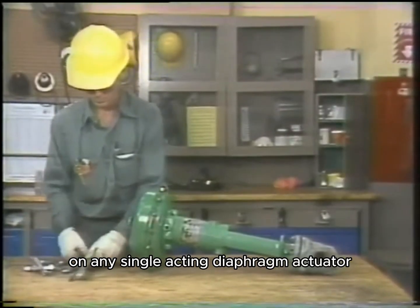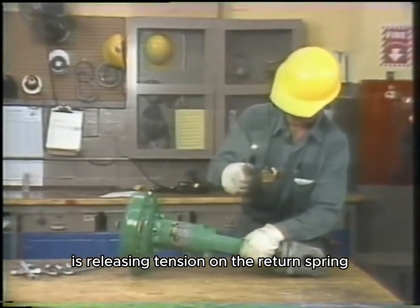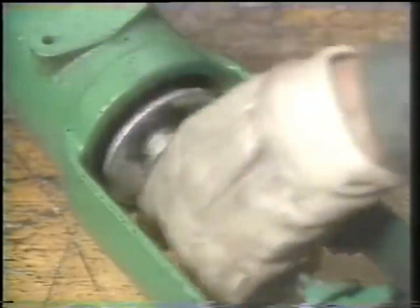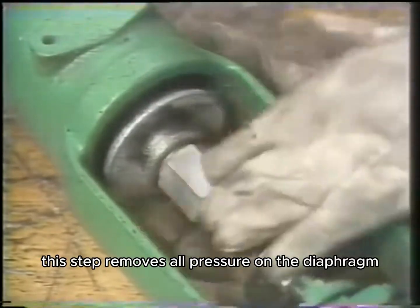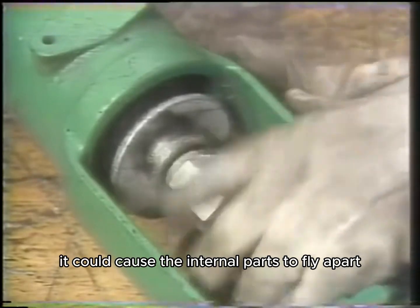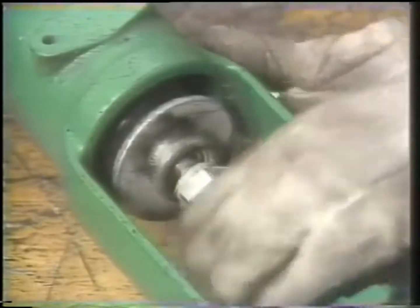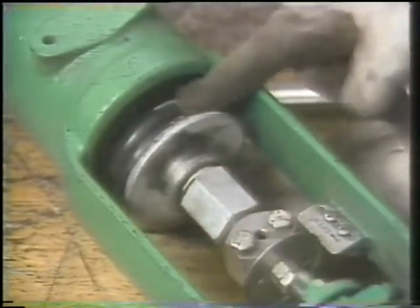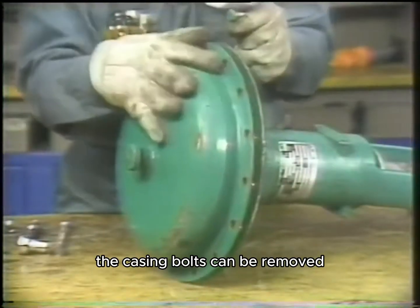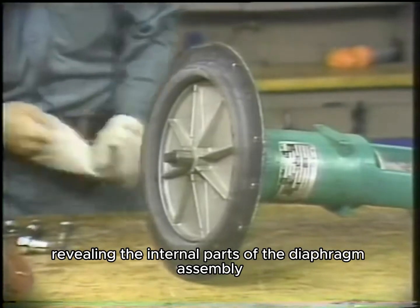On any single-acting diaphragm actuator, the first step in the disassembly procedure is releasing tension on the return spring. On this actuator, spring tension is released by loosening this nut on the actuator stem. This step removes all pressure on the diaphragm. If spring tension is not removed, it could cause the internal parts to fly apart as disassembly continues. When the nut's completely loosened and there's no tension on the spring, the casing bolts can be removed. When they're all out of the way, the casing can be removed, revealing the internal parts of the diaphragm assembly.